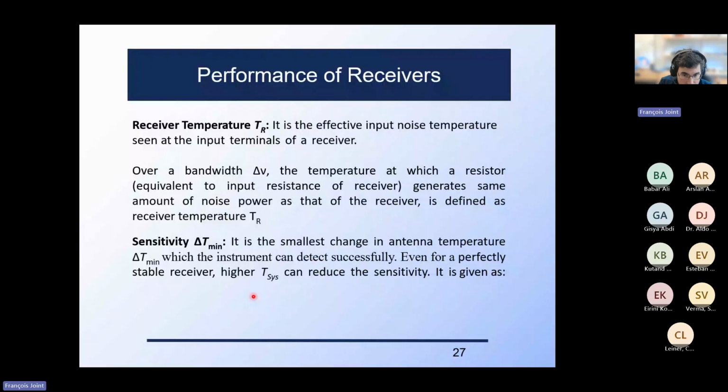I will talk also about stability. It's something that you would hear a lot also in radio astronomy. It's how long we can integrate a signal before we have 1/f drift dominate the noise. And of course, linearity and the compression points.